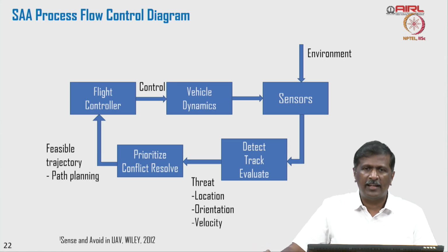As we discussed in control system design, it's basically a trajectory following controller. This local path is your local trajectory. The aircraft will start following the local trajectory. It generates a control input which goes into the vehicle. I have to keep monitoring the environment until the threat is no longer in place. Okay, this is the typical flow diagram used for the sense and avoid task.